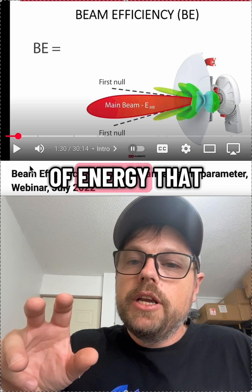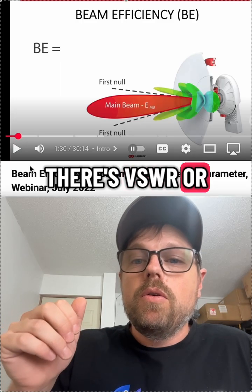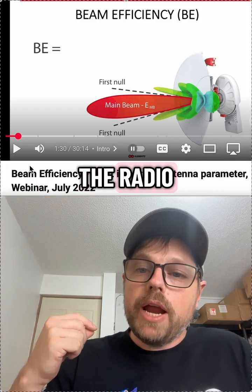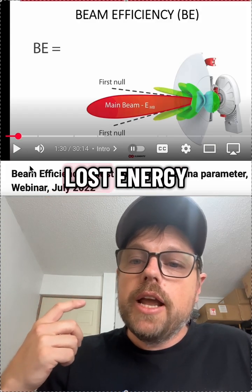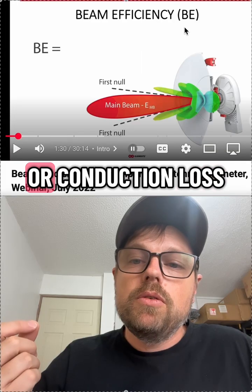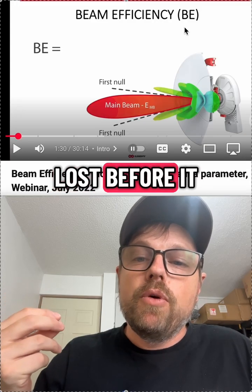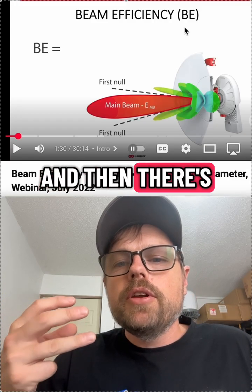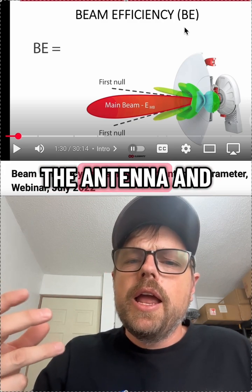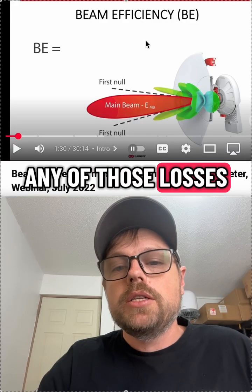There's a lot of energy that is lost before the energy radiates. There's VSWR, or return loss, which is the amount of signal that an antenna reflects back at the radio. And that is lost energy, but not accounted for with beam efficiency. There's cable loss or conduction loss, where the electrical energy is lost before it is converted to radio waves. And then there's loss within the antenna too, due to things like the radome, where the energy is absorbed by the antenna. And again, it's not radiated. So beam efficiency doesn't account for any of those losses.